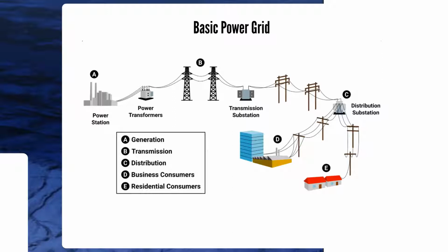An example of this source could be the use of coal. With coal, you will have chemical energy burning in a furnace, then you get heat, then that heat goes to water, then steam, then that steam goes to a turbine. That turbine rotates and produces mechanical energy. That then goes to the generator, and the generator will then convert mechanical power into electrical power.